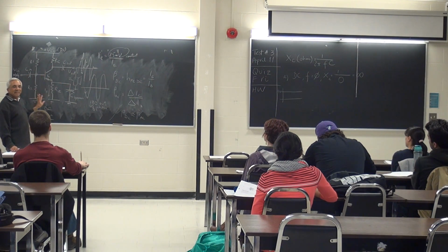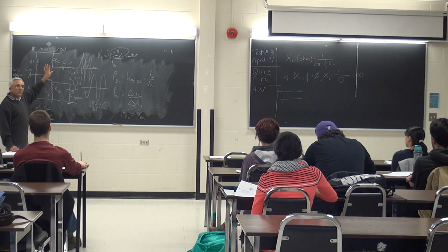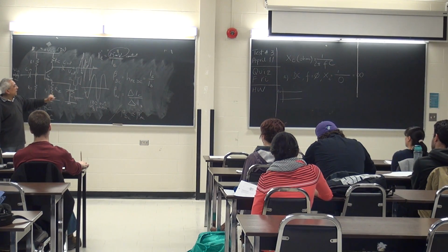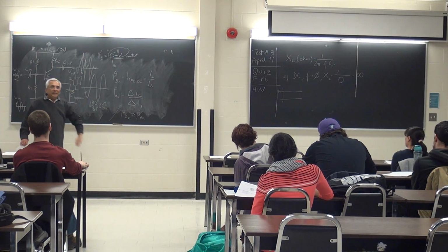So am I just left with the voltage divider circuit? So with DC analysis, I don't have to worry about the AC signal here. I don't have to worry about the capacitors here because they're open.